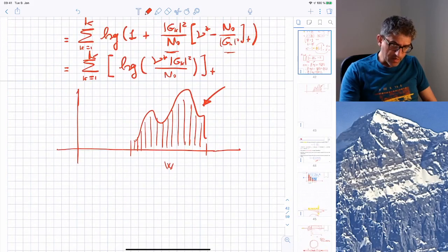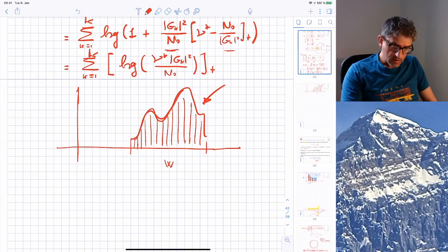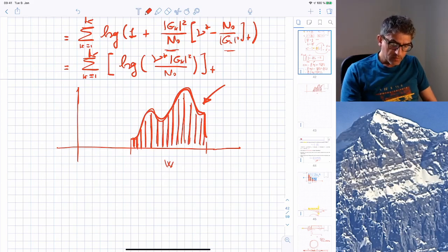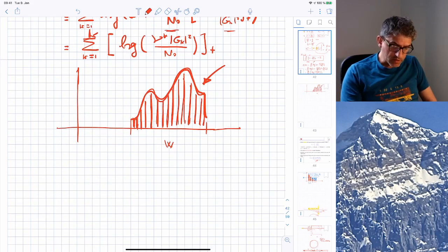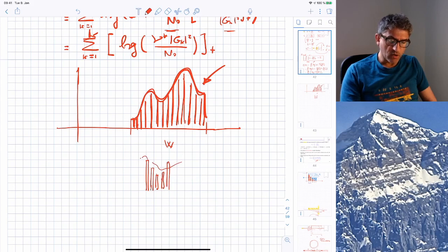I said, well, we have a channel with some transfer function, and we slice this channel into tiny parallel channels in the frequency domain. Each one has a very small bandwidth, so in each of these bandwidths, the channels look constant, so frequency flat, there is no intersymbol interference, but they have different powers, okay? So then we have to allocate the energy across the frequencies.